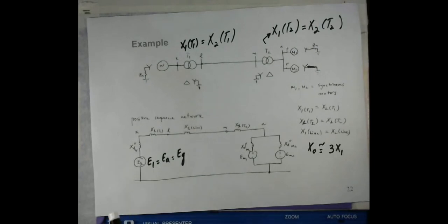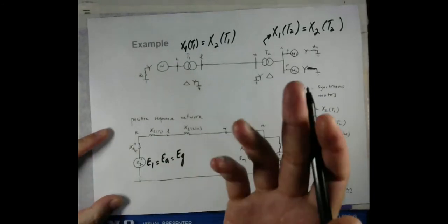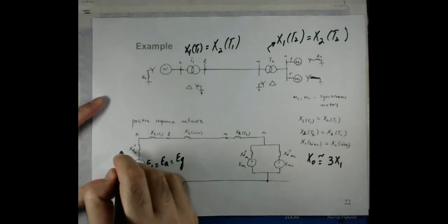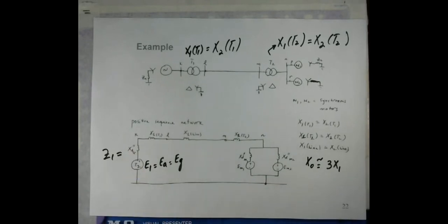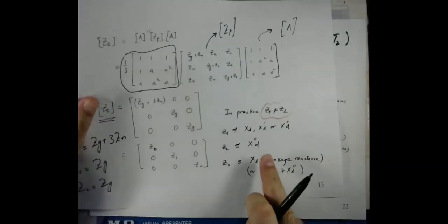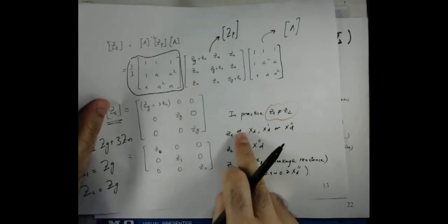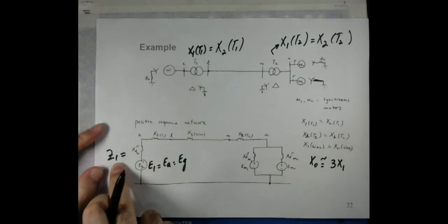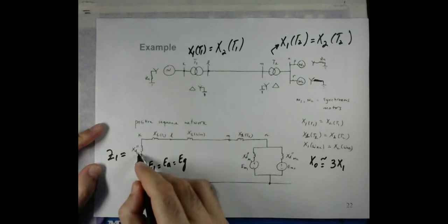Now, using that information, we are talking about the positive sequence, so we will consider either of these terms. In this particular case, X1 or Z1, if we are only talking about the inductive reactance, is taken equal to the subtransient inductive reactance. As I mentioned, Z1 can be any of these terms. In the positive sequence network, Z1 represents the positive sequence impedance, so it is taken as the subtransient inductive reactance of the generator.